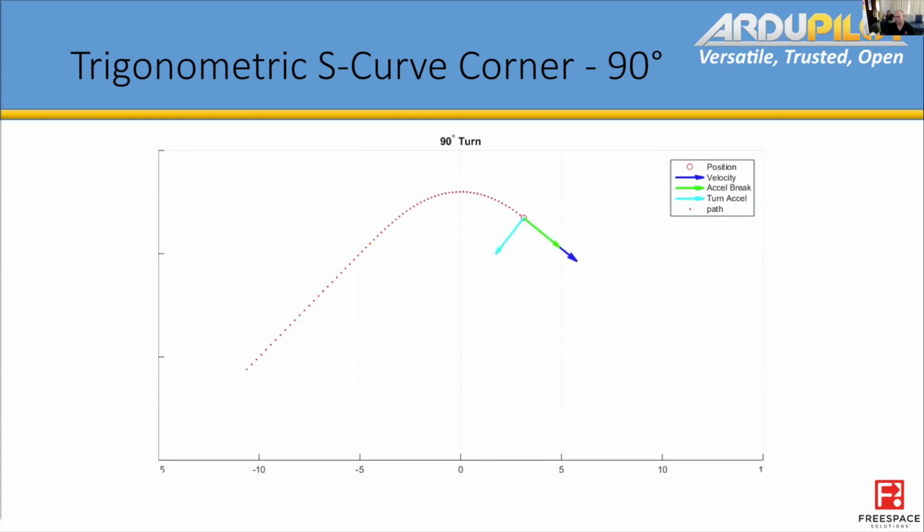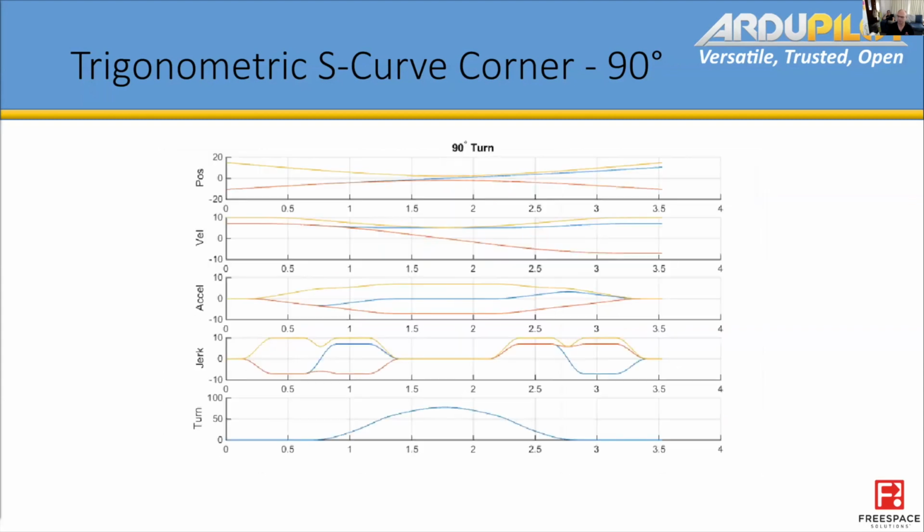So this looks great in the air. You can change the velocity and it will follow precisely the same track through the corner. Sometimes if you're going slow, below your maximum corner velocity, the corner will get a little bit tighter, but that just means that you get close to that waypoint corner, but it never goes further than your waypoint radius. So it's a really well-defined corner geometry.